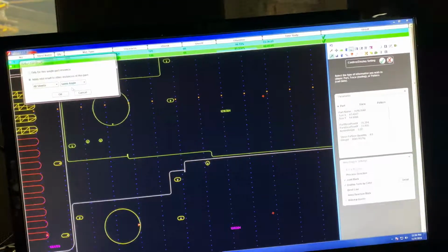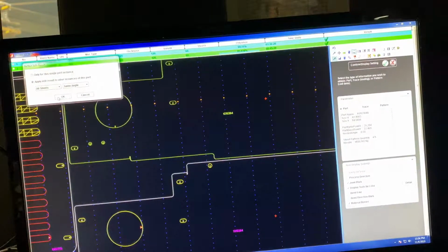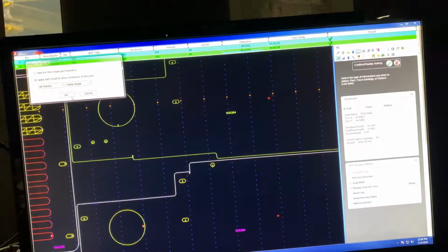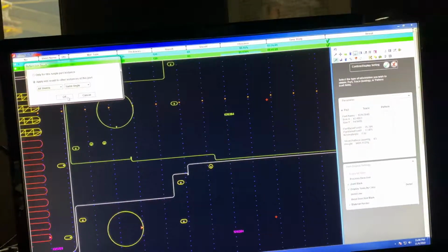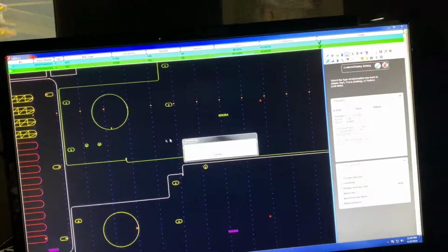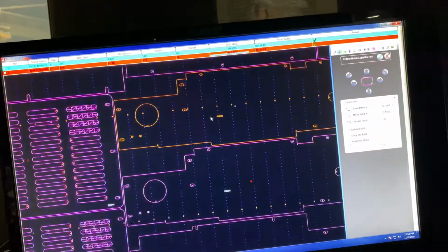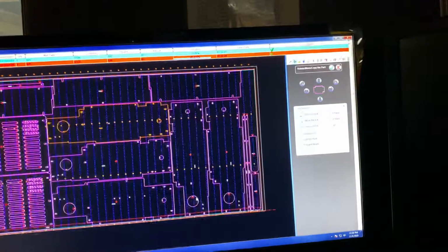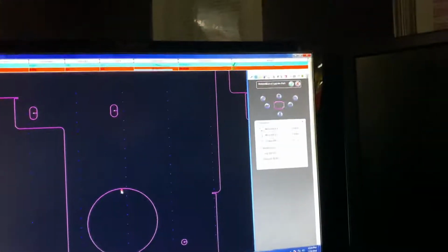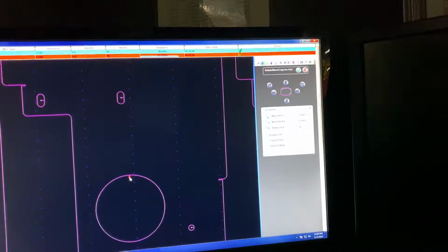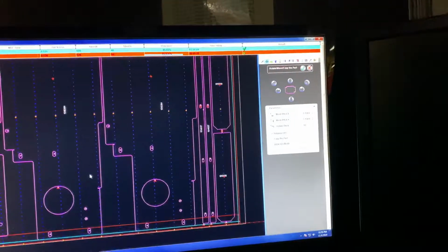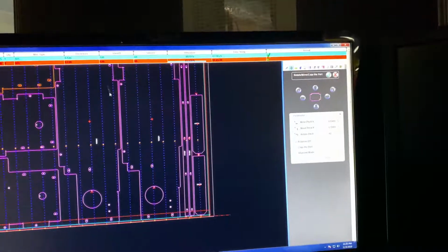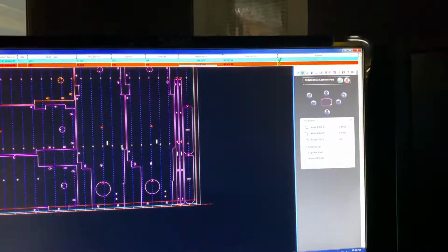So let's say you put a tab on this one, or you took it off because it was going to hit or something. Just click OK, and it's for the same angle. It'll take it off all the ones with the same angle, but keep the tab on, or whatever else you change on that part file, if it's going in a different direction.